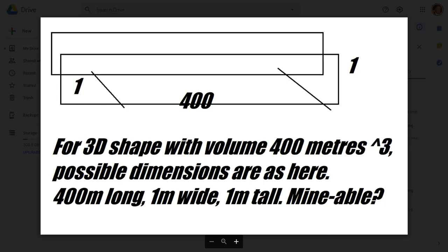Like, if ore chutes are running vertically and the face is gone, but you can see ore in the floor or something like that, go down on it with one of these robot things, and you can install safety equipment to buttress the rock in that area, kind of like isolate your effect on it, because potentially those ore zones are important structurally, and taking them out can be impactful on the geotechnical stability of a unit of rock.